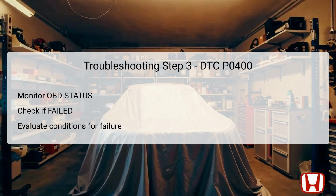Following the driving tests, the next step is to monitor the onboard diagnostics OBD system status for DTC P0400 using the Honda Diagnostic System, HDS. You will be looking for whether the status indicates a failed or passed condition. If the HDS shows failed, it is likely that the EGR valve needs to be replaced.